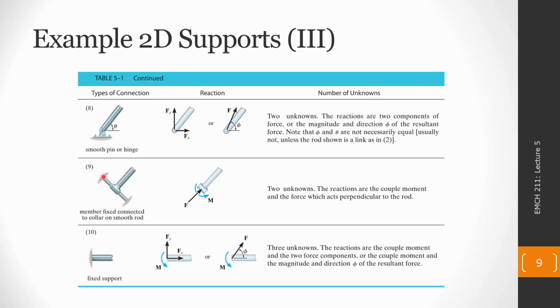So in our model here, we are modeling that prevention of rotation as a moment or as a couple. We don't know its direction because this can't rotate clockwise nor counterclockwise. So we can just assume for our picture and then for our equilibrium equations that the moment that the collar is going to exert on the member that we kept is positive counterclockwise.